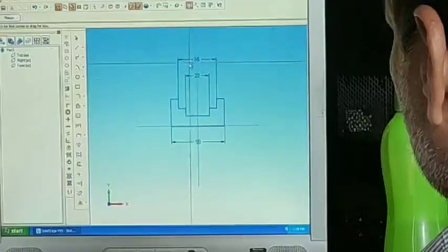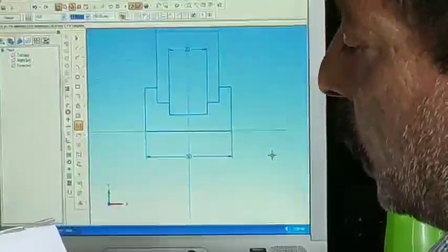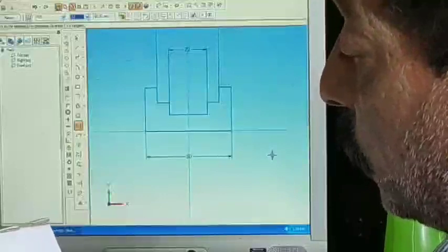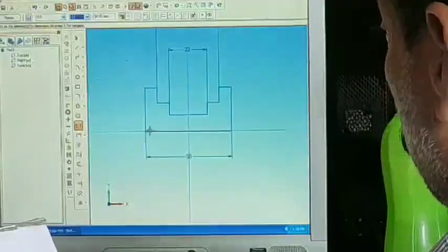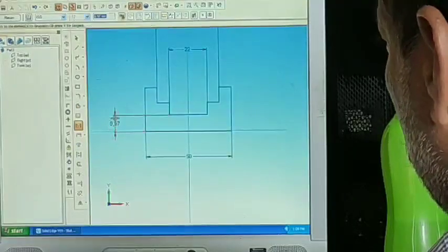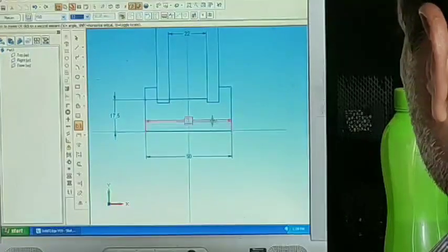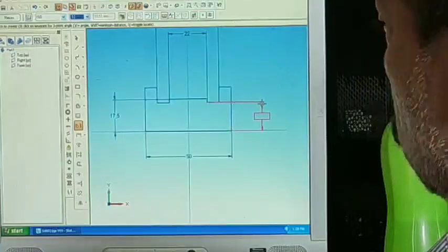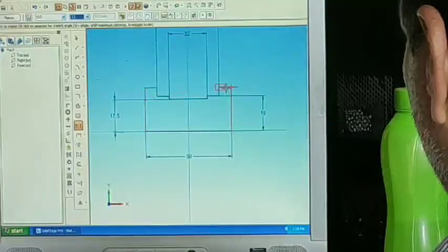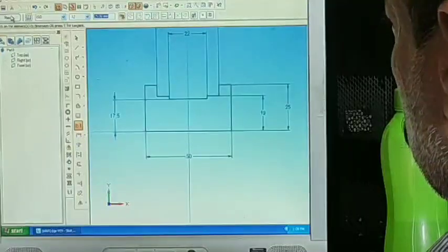So next diameters wise I am coming. So first diameter is of 35, second is of 38 and third is of 50 mm. Since I am in revolved protrusion, so you should take it as half of that one. So first go to small dimension. This is 35 diameter, take it as 17.5 mm. So next diameter is 38, take it as 19. So next diameter is 50 mm, take it as 25 mm. Right? Return.